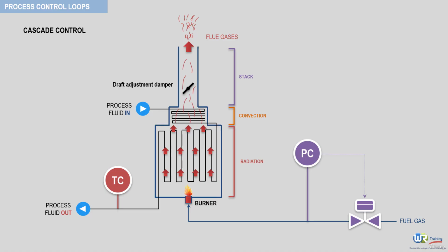Nevertheless, many disturbances that the pressure controller cannot counter are able to vary the furnace heating capacity and consequently the outlet temperature. These disturbances may be countered by a more sophisticated control system. The primary loop has the same function as if the valve signal of the temperature controller directly drove the valve.